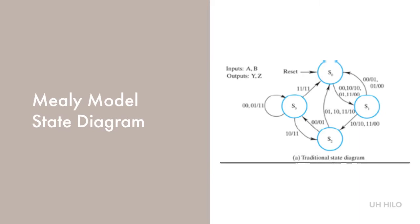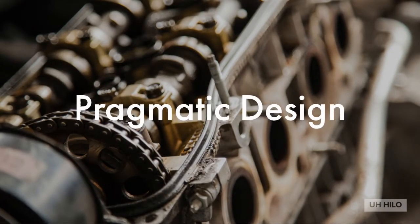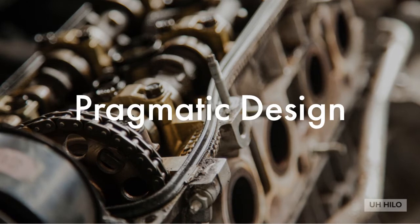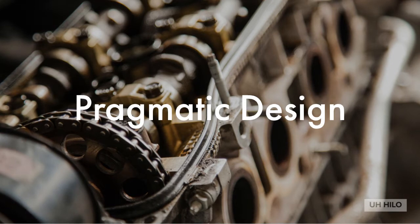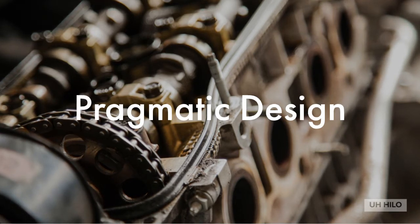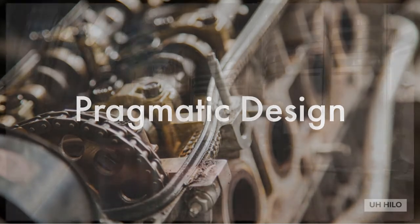The Mealy model is not very efficient in specifying outputs because of the need to combine transition and output control functions together. To overcome these problems, we'll use something called a state machine diagram. The main targets of the notation changes are to replace enumeration of input and output combinations with the use of Boolean expressions and equations. This will help us describe input combinations and expand the options for describing output functions beyond those permitted by the traditional model.